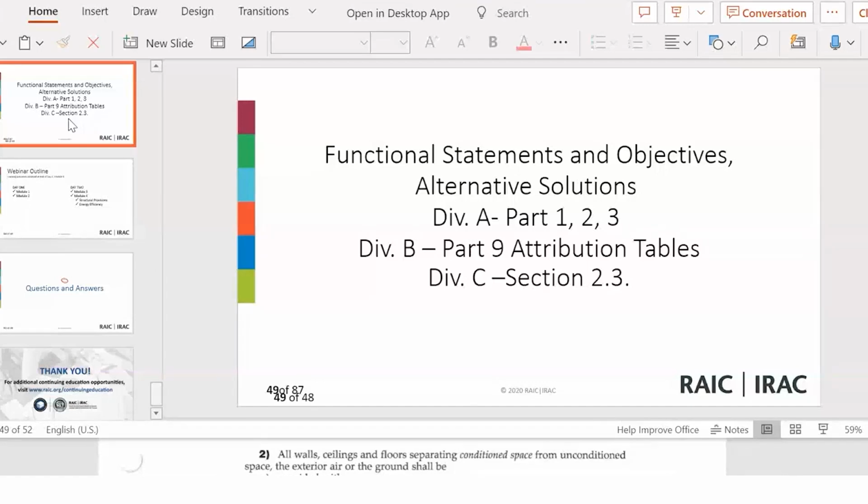And of course, you've got your site plan, and this is where you work with the civil. You look at your access roads, and you look at property lines, and you look at how you're going to consider the garages for basement. If you have basement garages, are you going to consider it a separate building? Are you going to consider it part of your building? So that's another major question that you deal with right away, in addition to accessibility for fire department to your buildings.